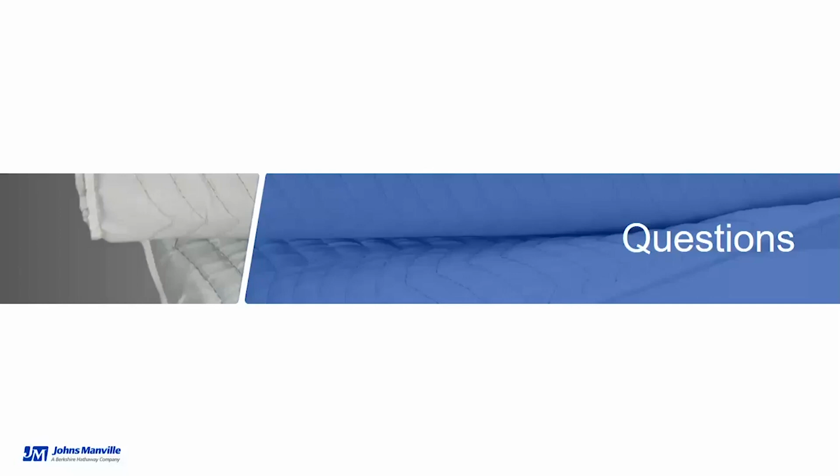question is, do you have any specific recommendations for handling procedures, cutting tools, installation practices, et cetera, to minimize worker exposure to particulate? And Kelly, I'm going to hand that to you to just talk a little bit about the PPE. Yeah, so I would definitely recommend that regardless of whatever system that you're installing, you follow the manufacturer's recommendations, both on the technical documents and also on the associated product safety data sheet.